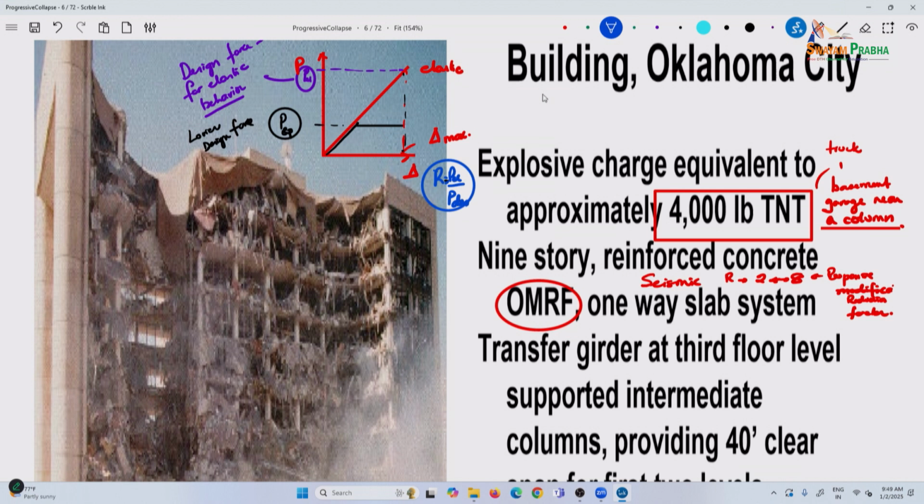and we are also doing the same thing in blast. We are also doing exactly the same thing, but we are now considering it in terms of delta. This is Y max, Y elastic, and then our mu is Y max by Y elastic. In a way, you can try extending this out. So, it is a similar ratio that we are talking about. So, when seismic you see 2 to 8 and we are getting even higher values.